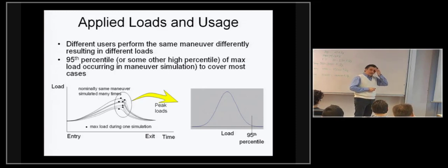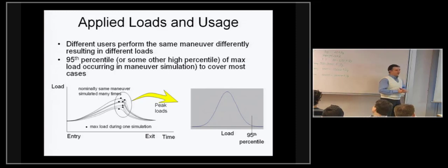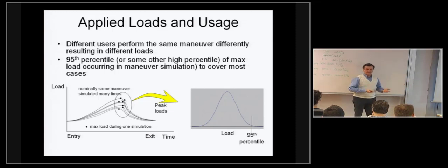The applied loads that we take for granted, aerodynamic loads or whatever else, are never known extremely accurately, irrespective of how advanced your fluid dynamics, aerodynamics codes might be. You only can calculate those to within a certain approximation. And even if you have those reasonably accurately, whatever that might mean, translating those now to internal loads in your structure through, for example, some kind of a finite element model, again involves certain assumptions and certain approximations.